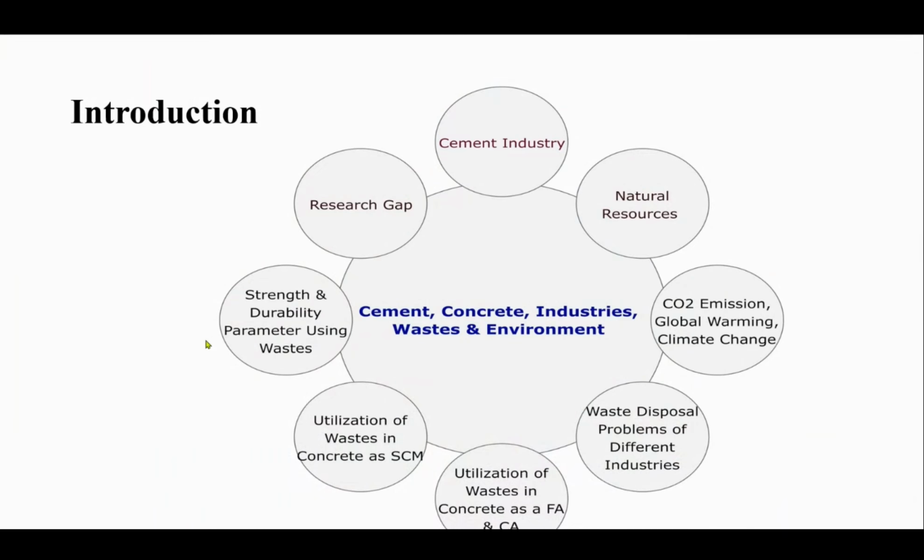But whenever we use that waste in concrete, it is not to show people that yes, we used that waste and did it. It is not a show-off. We are actually giving industry a solution: in place of natural resources, we can use steel industry waste. To give the exact idea about the results, we have to go for experimental work on concrete. It is not like I cast one cube and tested its strength, and that is enough. That will not happen.